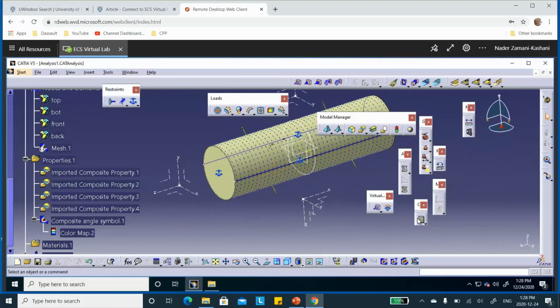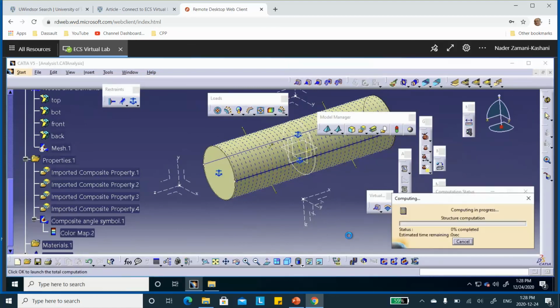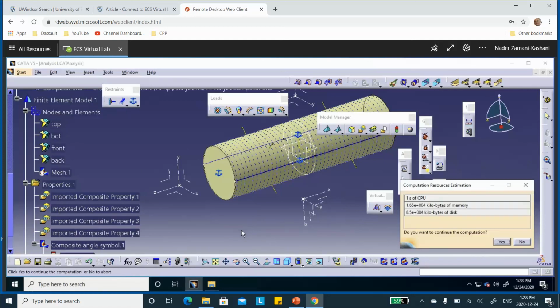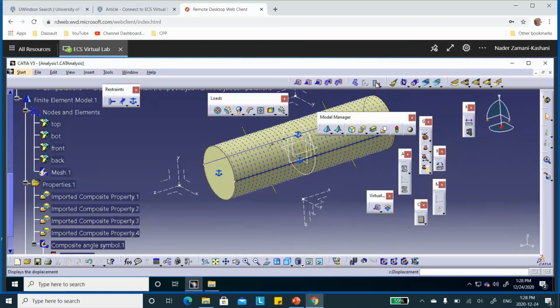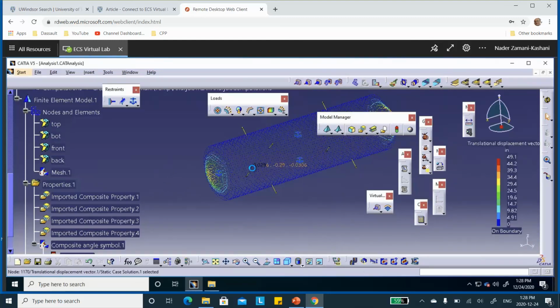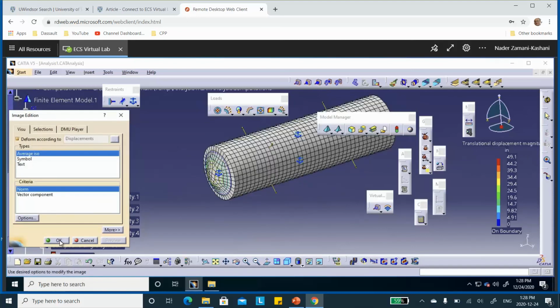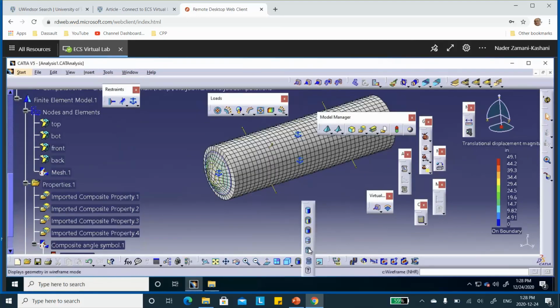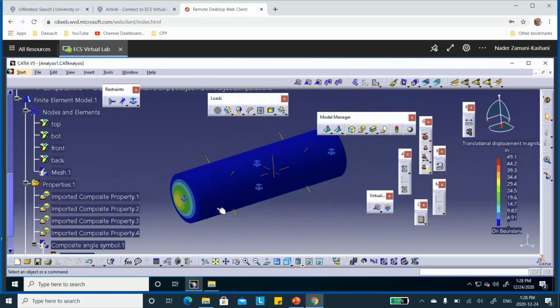Run it, but make sure it's not mesh anymore. So it's going to do the calculation. Say okay. Done. Let's look at the deformation. Looks good. Change the thing to average ISO. Change the rendering to material shading. This is what I expect. Okay, the ends will bulge out.